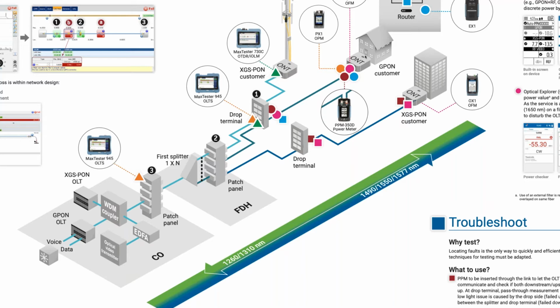So on this particular unit, I have a 1625 filtered port, and if there were light on this circuit, I would be able to shoot from the 1625 filtered port and not impact the customers that are on the network on the other side of the splitter or anyone else. But that would be testing during the troubleshooting or after we've already deployed and connected customers. All right, so this is a little bit better trace, something that we can more easily look at. And it actually fits exactly with my PON simulator.